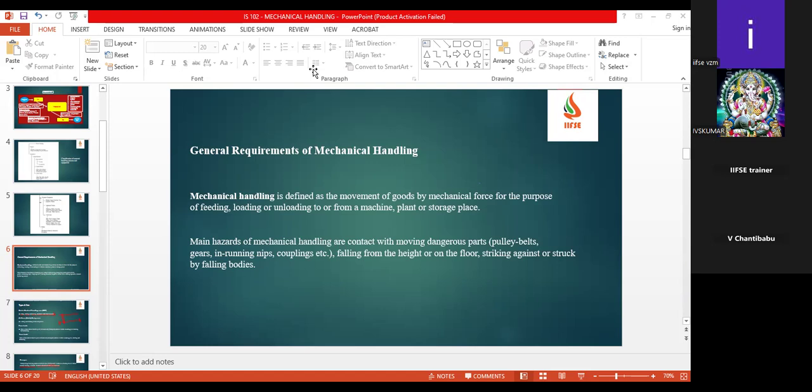But what they do is they check the diameter of the rope with a gauge, a vernier caliper. They see whether any elongation happens or there is a lubrication problem. They also check the standard slings for any damage or rubbing. That's why they check at high level. The service provider will bring the load to site to test the EOT crane, but calibration people won't bring all these test blocks. Okay, sir.